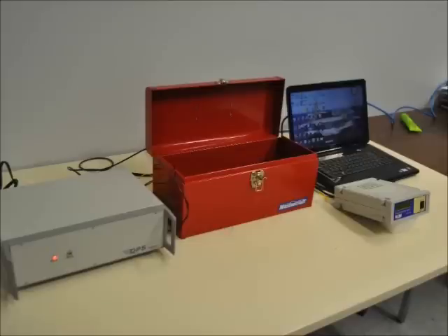The PD sensor is mounted to the walls of the toolbox just as we would mount it to the walls of a transformer. The piezoelectric actuator is immersed in oil and creates bursts of acoustic emissions. These are the same signals that would occur during partial discharge in a transformer. Various frequencies simulate different PD processes, such as defects from cellulose paper or air bubbles in the oil.